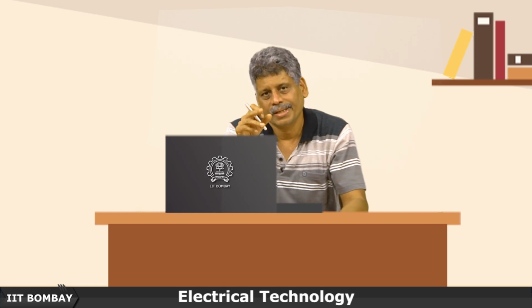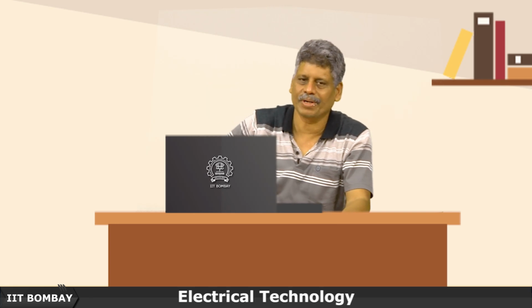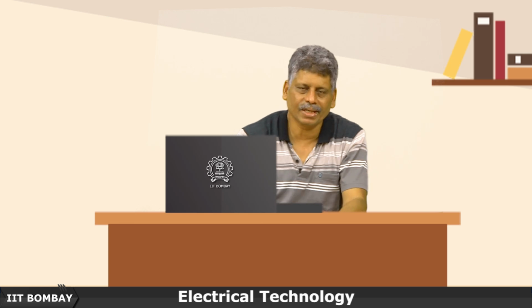And then finally, when it comes to your residences, there is somewhere a transformer nearby which would have finally brought down that 22 kV also to 400 volts three phase level, and then you get it in your home supply. So, it is like crossing a ghat section or a hill. You step up the potential, again climb down and step down, again climb up, and then again step down the potential.